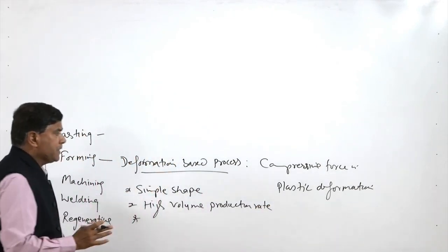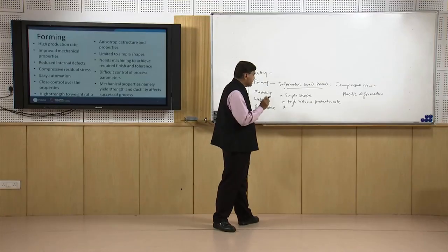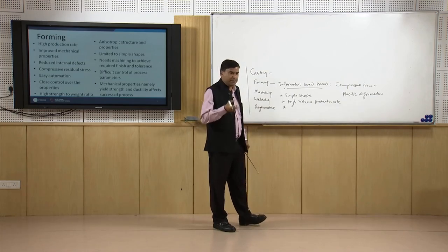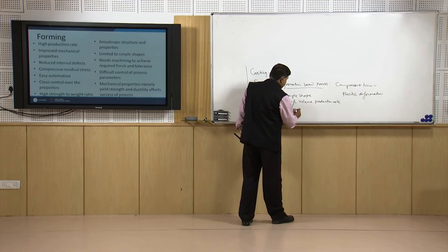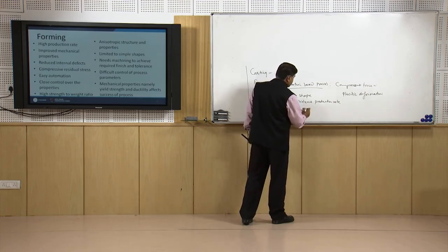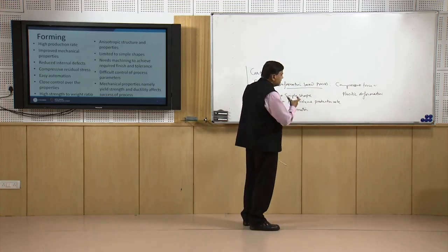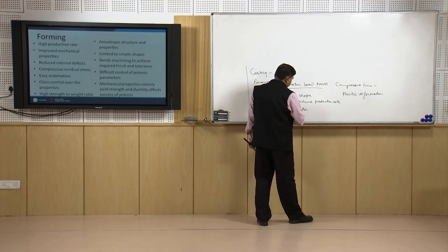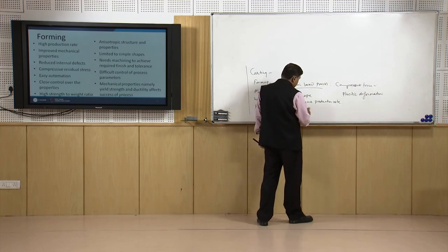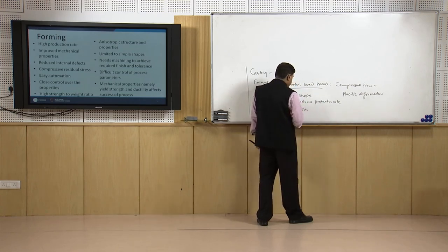Generally, the deformation is associated with the closing of the discontinuities and the defects if they are present in the material. So, basically it eliminates impurities, defects and discontinuities if they are present under the compressive plastic deformation conditions. These are eliminated from the raw material.